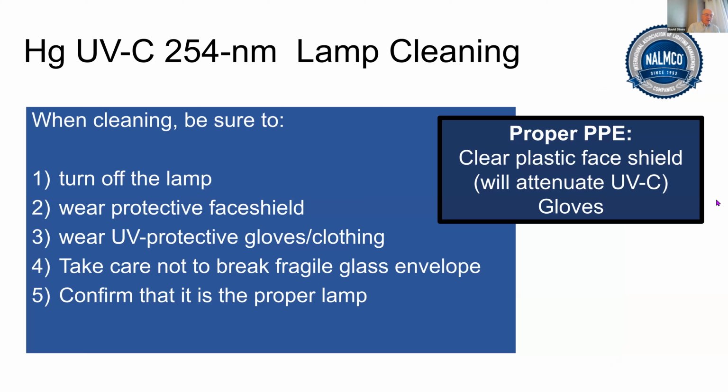You need to wear a protective face shield. You need to wear UV protective clothes, gloves, if you cannot turn the lamp off. But the most important approach is just to be sure that the lamp is turned off while you're doing this. You also want to be sure to confirm that it's the proper lamp. Unfortunately, there have been cases where people have taken a germicidal lamp and put it in an insect attractant lamp, and people got injured from